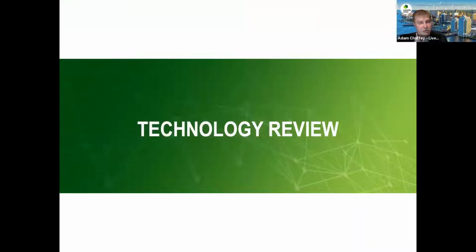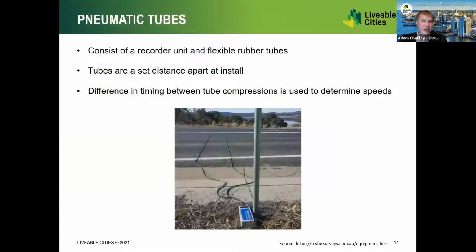So just to share with you a little bit of a review of what exists for this technology. Traditionally, pneumatic tubes such as these were used for a lot of these types of studies. We are a little bit restricted in what data we can capture and the duration over which we can capture it. So these devices typically have to be secured to a road sign or other fixed asset, so they can't be vandalized or removed or stolen.